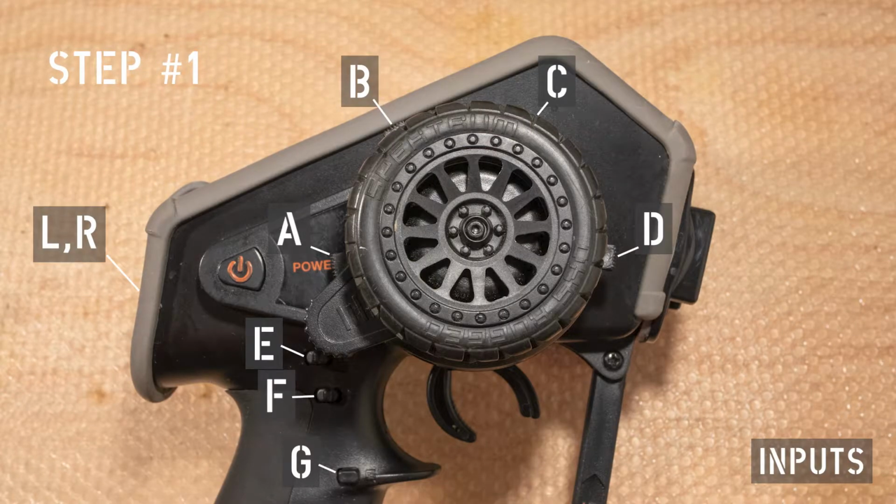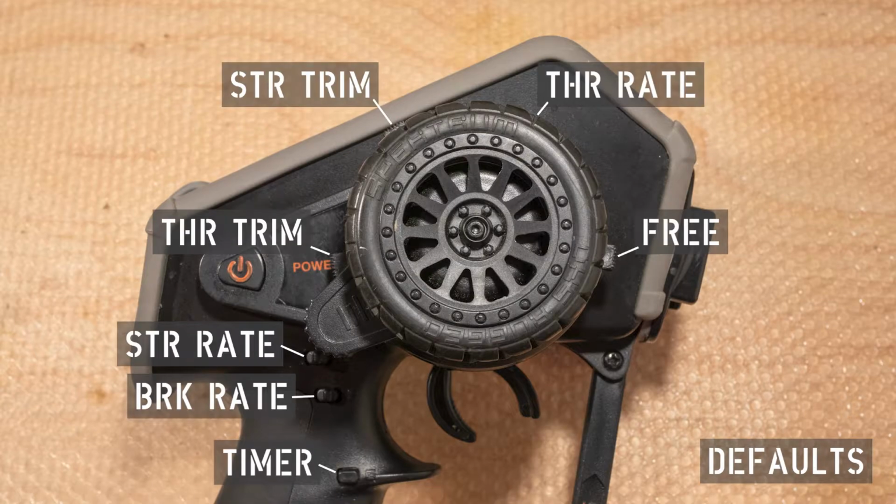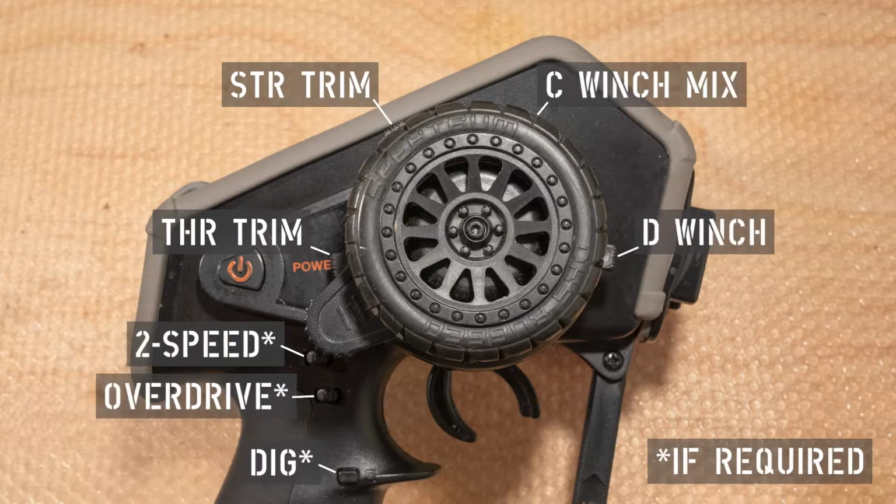The first step is to choose which radio input you want to use for on-the-fly mix activation. The DX5 Rugged has 7 primary programmable inputs labeled A to G. You can use any of these inputs, but it should not have any other function assigned to it. If it currently does, remove that function before continuing. I like to use E and F for shifting servos and G for dig. I use D for normal winch control and switch C for winch mix activation.